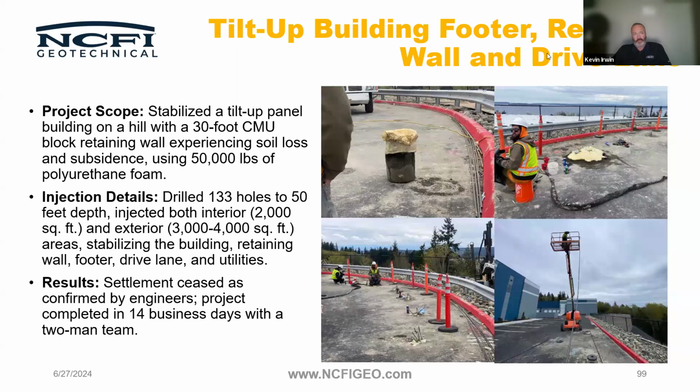The foam doesn't have to, we're not trying to get foam inside every bit of soil. What we're trying to do is allow the foam to get into the soil it can get to, and then it's pushing the rest of it and compressing it and giving that soil its density back. Now, if it's a water soluble soil, eventually that may start to leak in, and you may need to put some different chemical back down in.